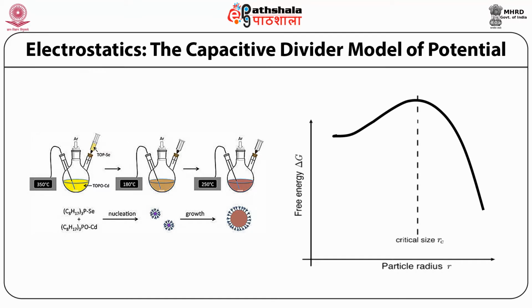In the case of spherical nanoparticles, we neglect any variation of the surface tension sigma, that is, nanoparticles without facets. In this case, the number of atoms small n in the previously discussed equation can be expressed in terms of the radius small r of the nanoparticle and the density of atoms in the nanoparticle, and here in this case delta G equals 4 pi d by 3 multiplied by r cubed multiplied by (mu_C minus mu_S) plus 4 pi r squared sigma.